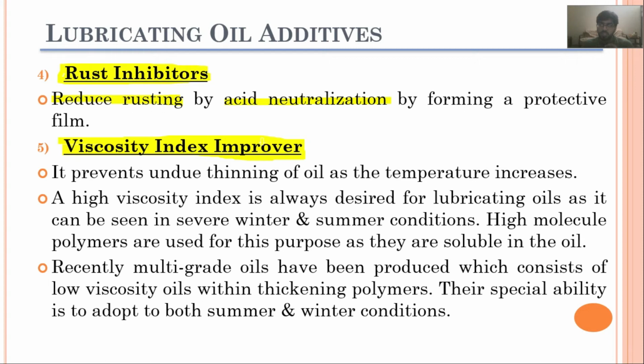So the changes in the viscosity would be quite low. It means that it will have a higher viscosity index, so the viscosity index will be improved. A higher viscosity index is always desired for lubricating oil, as it can be seen in severe winter and summer conditions. For that purpose, high molecular weight polymers are used, as they are soluble in oil.